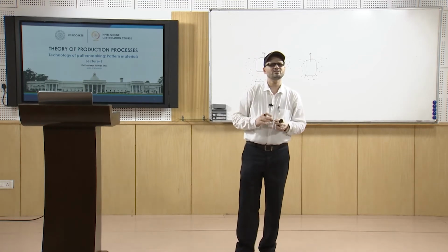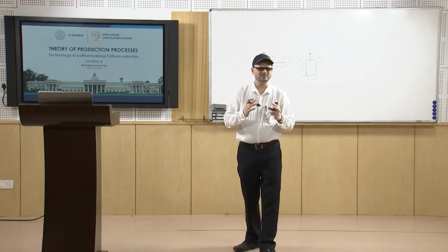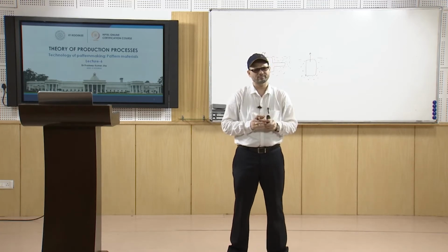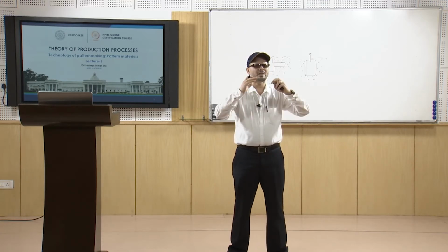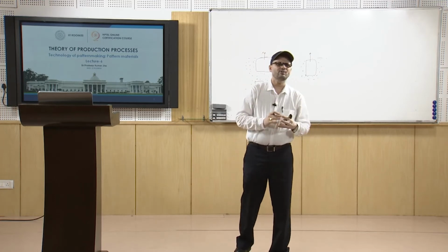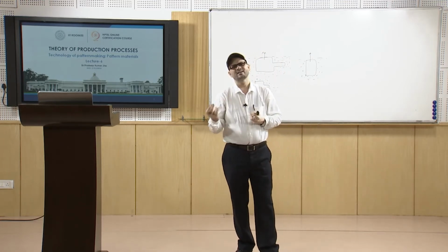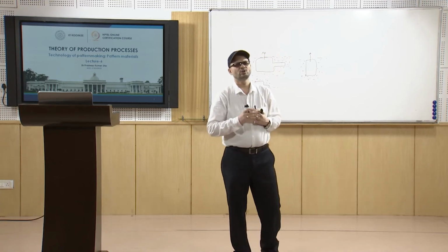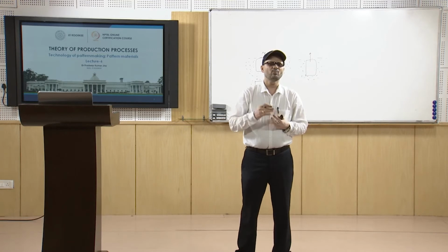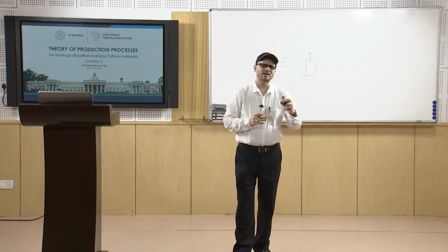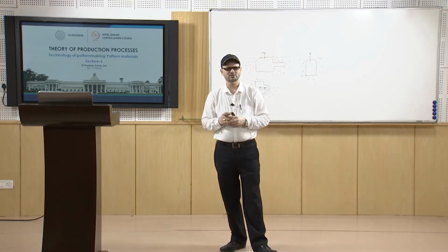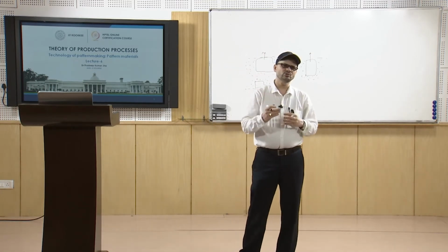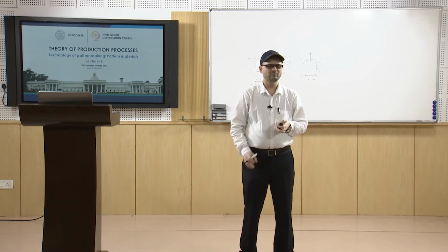Also the dimensional precision, as we discussed: when more precision is required, you will have to go for a material whose dimensional stability is more, like metals, for which it is normally more than that of wood. So, that way you are going to use different materials. Molding process: you may be using a manual molding process, or a machine molding process. Based on that also, what kind of pattern you are going to use varies.